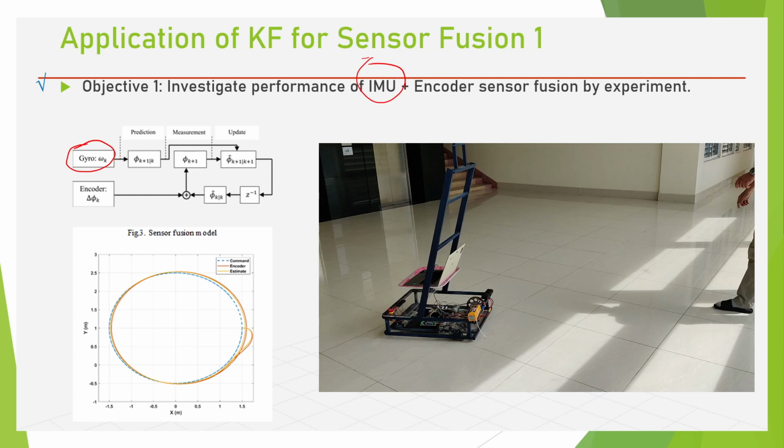It means it's telling us that the robot is moving a little bit, but it's not true, right? So at low velocity or at rest, the encoder information is good, but the IMU information is not good. But when the robot moves fast, the wheel may slip, so the information from the encoder is much more wrong, but the IMU can give better information. So we choose these two to have a better estimate of the localization.